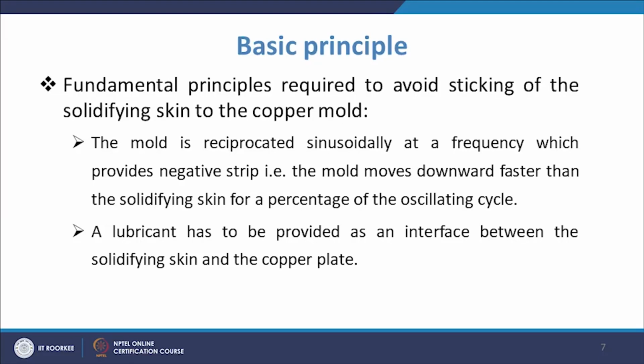Another thing we do is that we also apply a lubricant at the interface between the solidifying skin and the mold, which is made of copper. If a lubricating agent is applied, the skin will not have the tendency to get stuck or pasted to the mold, so it will go down.